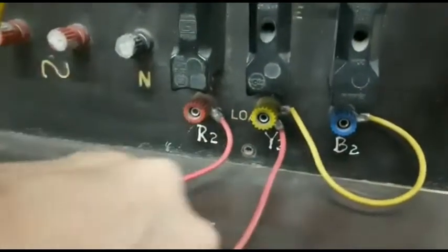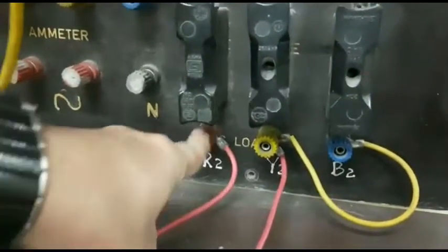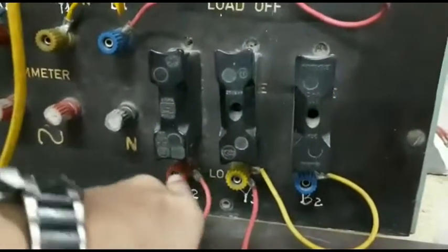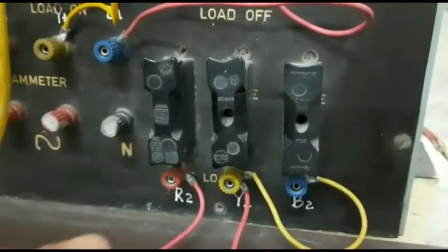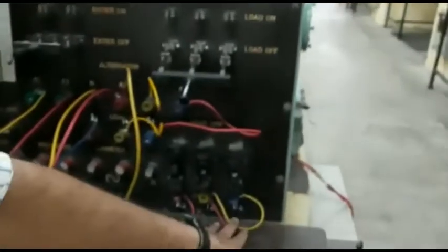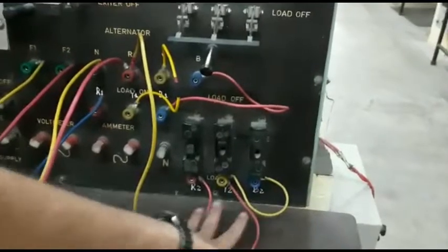It is very much clear in your circuit diagram that has been shared in the lab manual. You can see that all the 3 terminals are short circuited in a short circuit test. In the connection, you can short this in advance. While doing the open circuit test, you have to open this. That means that even though the 3 terminals are shorted here, no supply is coming to R2, Y2 and B2. That means that all are open circuited.